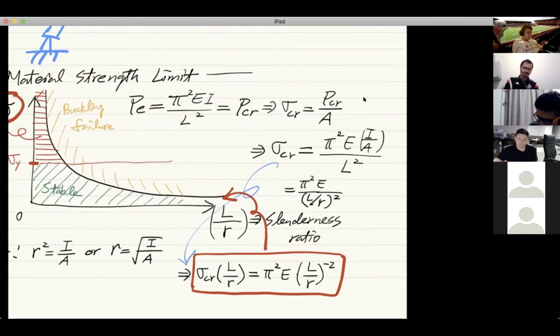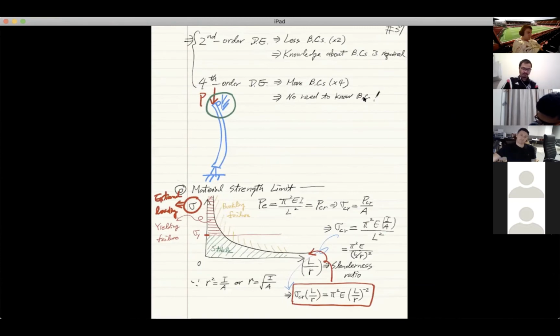And of course, from structural analysis, we talk about different methods, right? There's ASD, there's LRFD. For steel structures, you're using the ultimate load, which is PU, remember? And PU is from what? How is PU related to PY? PU is the reduced version of PY. If it's reinforced concrete, you use a nominal strength, with a PN or MN, nominal moment, nominal force, right? Then you also reduce that to get the ultimate strength.